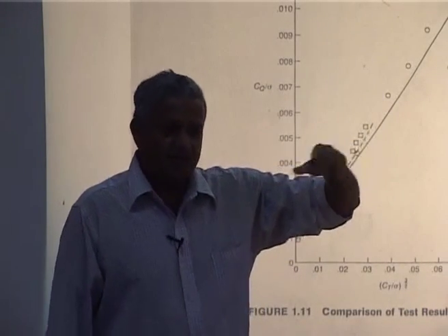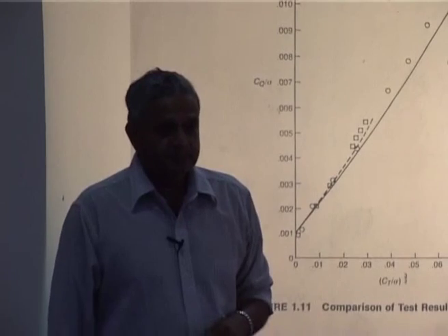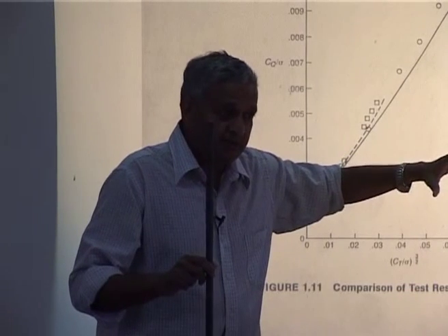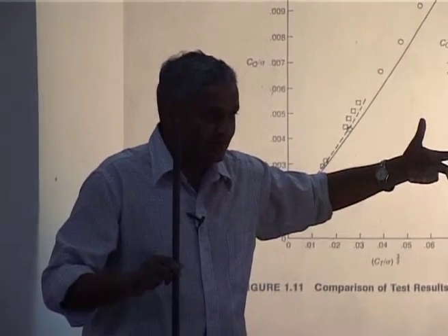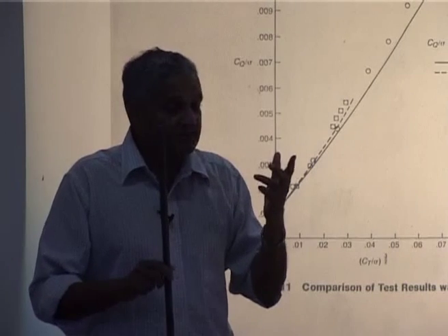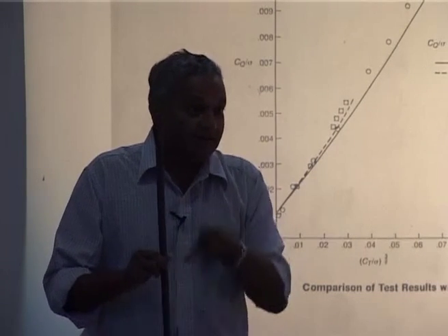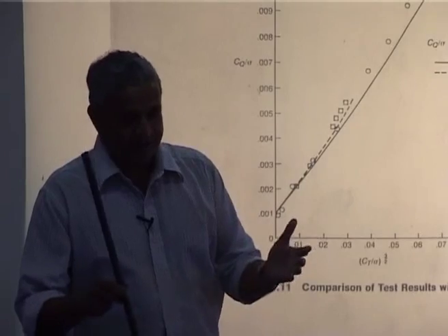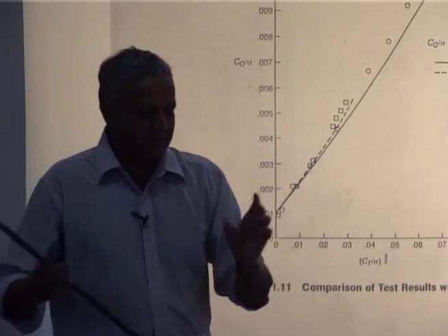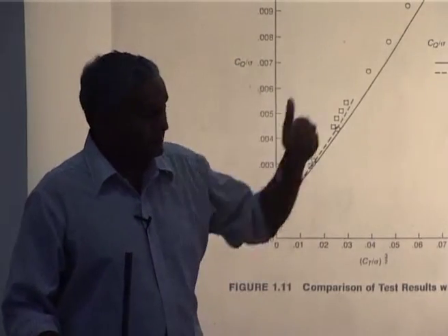Keep taking it to the extreme and you say beyond that my pitch link, because this is how it was defined, gets the pitch link load, because the pitch angle is moving, and the pitch link load is directly dependent on torsional moment, because when the blade stalls, torsion moment comes. This is a dynamic load. Please understand, dynamic stall means it is oscillating, your oscillatory load will increase, which is related to fatigue life. So they ask, where will I start having large oscillatory load? Now, what is large? You have to define some number. Okay, I have my limit of infinite life in metals, and then I will say 3 times the oscillatory load. If I get that in some situation, that means I have reached my limit, I cannot go beyond that.